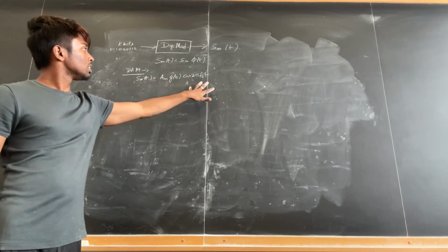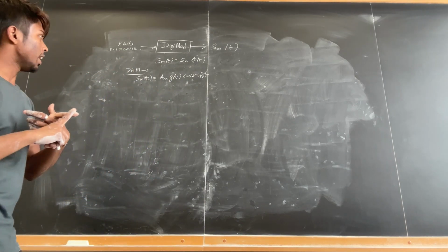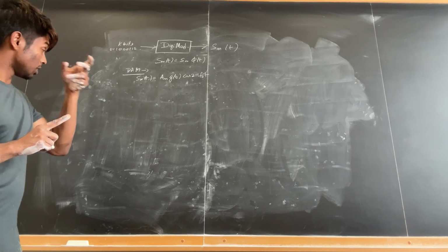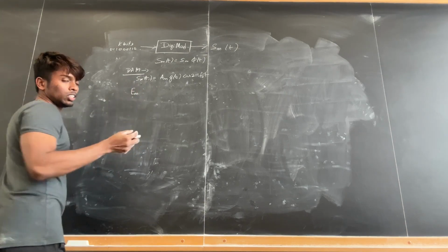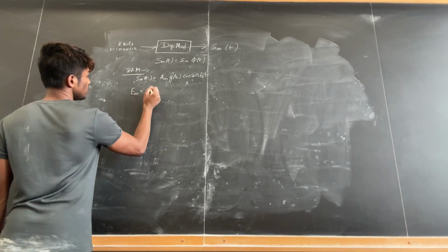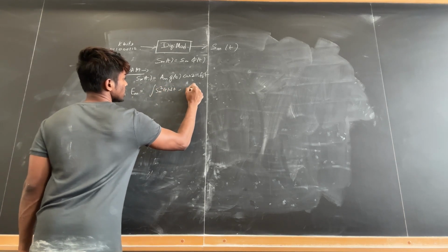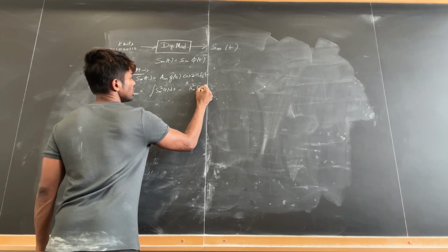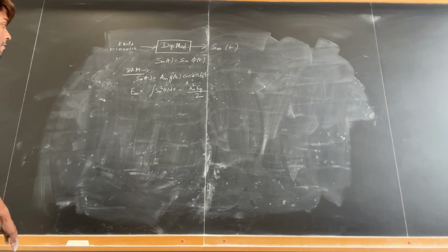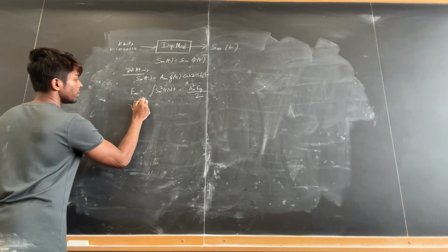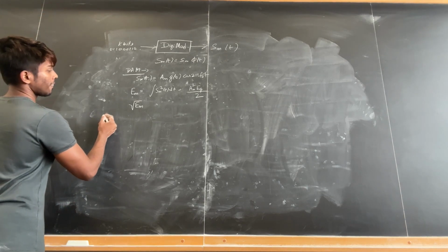In that case, s_m(t) is this, which we can also expand, keeping in mind the energy of the signal. So what is the energy of the signal for s_m(t)? We can compute the energy as E_m. So energy for the particular symbol should be the integration of s_m squared t dt. So this integration gives us A_m squared E_g by 2. So if we take this in mind, the square root of energy is basically the amplitude, that is s_m.